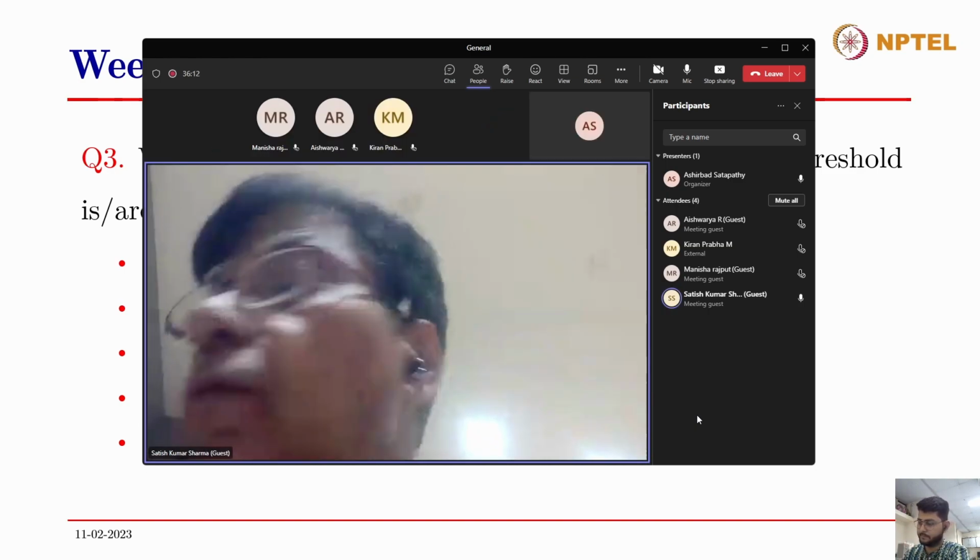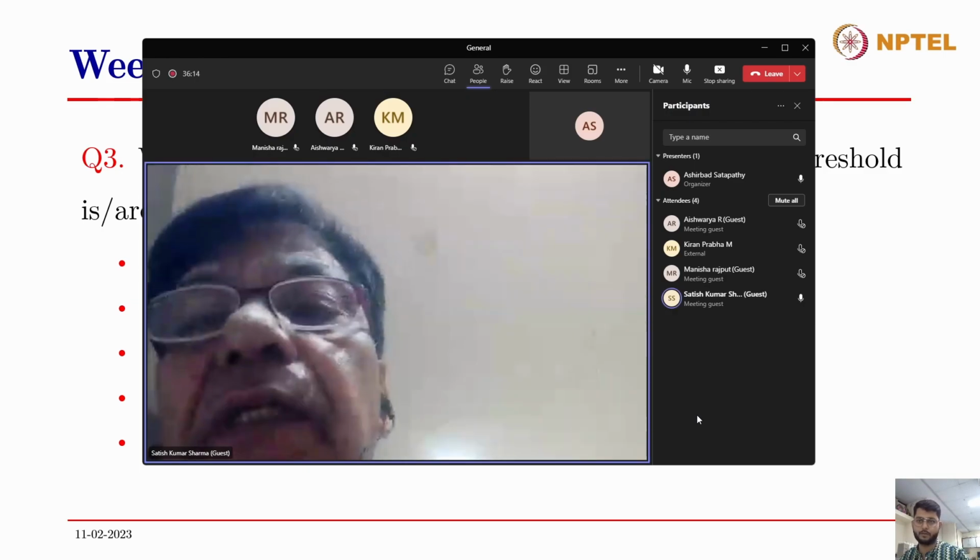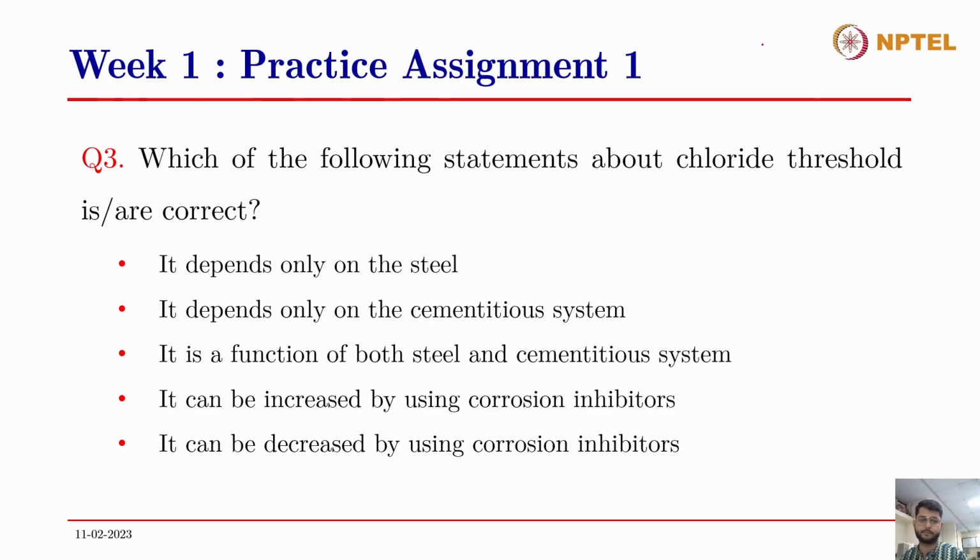The question is chloride threshold. It's a function of both steel and cementitious system. Then it can be increased by using corrosion inhibitors. So you want to say that the answers are the third and fourth ones? Okay, thank you, Dr. Satish.